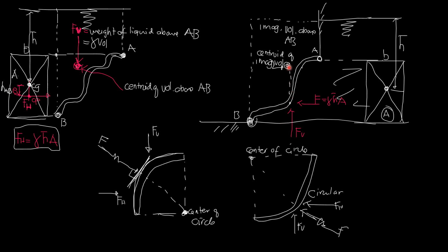That point is the centroid of the imaginary volume, or the centroid of the imaginary area if B is constant. So that's why the volume is just this area times B, because the centroid of the area travels by B. So volume is area times B, or area times H, remember, where H is the distance traveled by the centroid of the area.